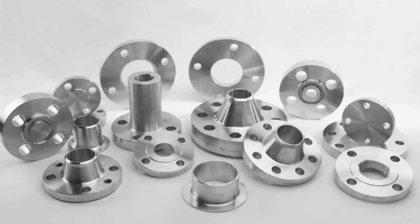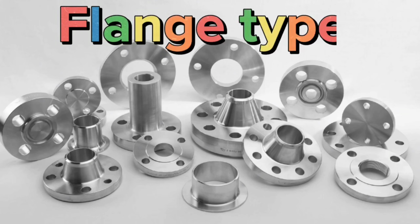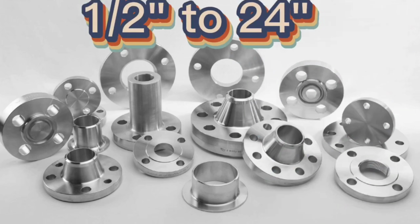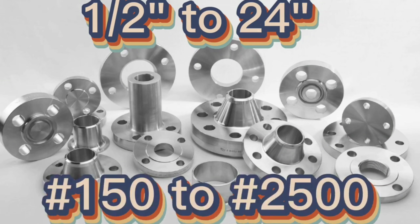In this video, we will learn about vital pipe flange types. Flanges are the construction element used to connect pipes, valves, pumps to form a piping system. In other words, it is the connection used to join the pipes. Flanges are standardized according to publications from organizations like ASME, MSS, API and others. Flange dimensions for pipes range from 1/2 to 24, in classes ranging from 150 to 2500.